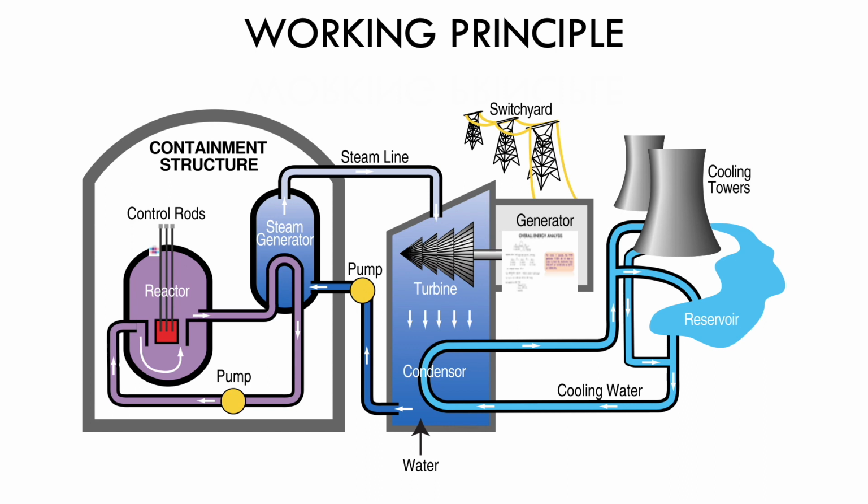This heated water then flows out of the pressurized reactor and comes in contact with the water inside of the steam generator. Water inside of this generator is not kept at a high pressure, hence when heat is transferred from the water with higher temperature, the water inside of the generator will boil and produce steam. The cooled water will be pumped back into the reactor for reuse.